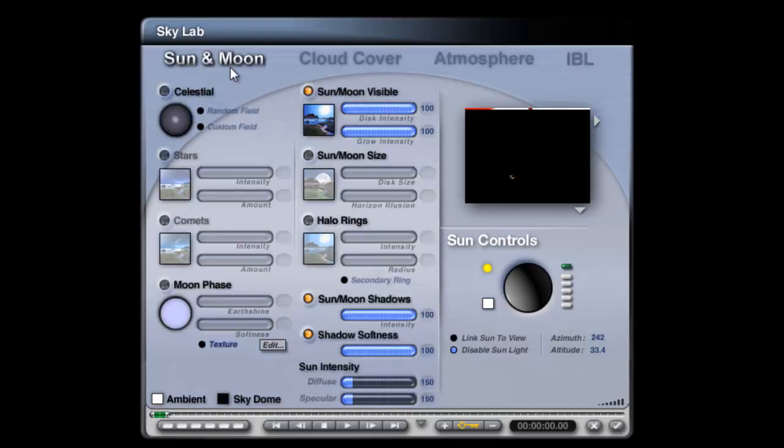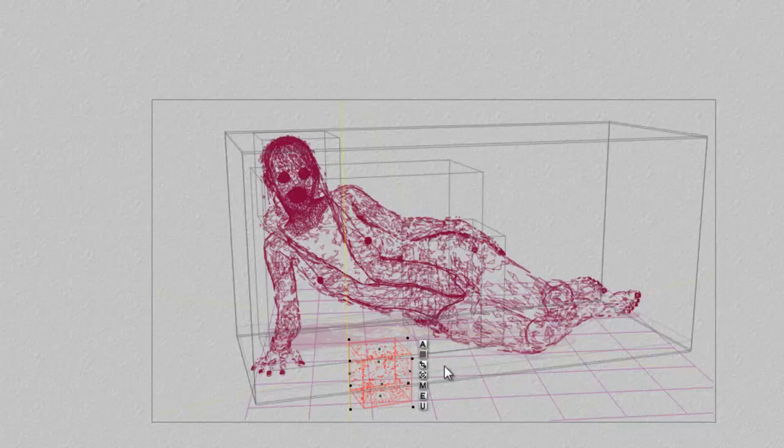So here we are done with the render, and it occurs to me that there is something that I could mention here. This material on this two-part cube has got a component that responds to specularity. Now I could re-render the scene with the sun enabled to just provide specular, but that will probably be rather time consuming, because it would have to calculate all the rays passing for the direct light in the form of specularity for all the scene and not just this bit.